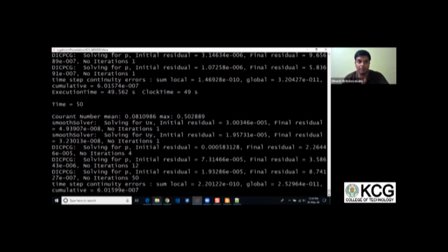These are very important terms, specifically to get a stable result, because numerical solution is a problem of instability. That means due to round-off error and truncation error and other improper settings of the conditions, you may find the solver may diverge. So you need to get to know these terminologies.